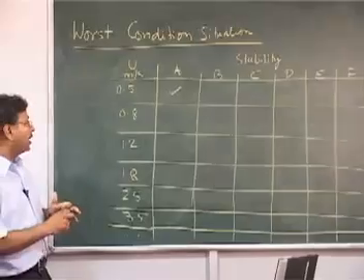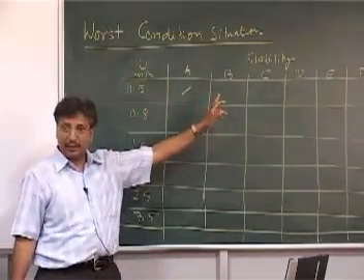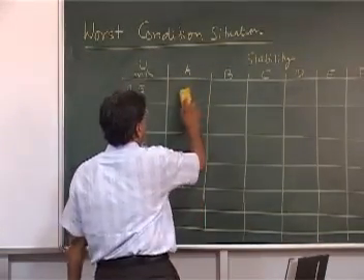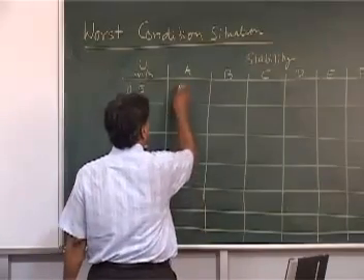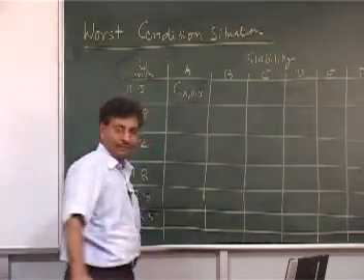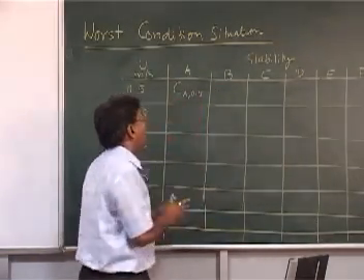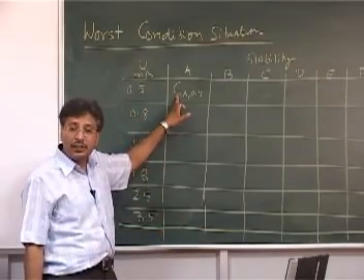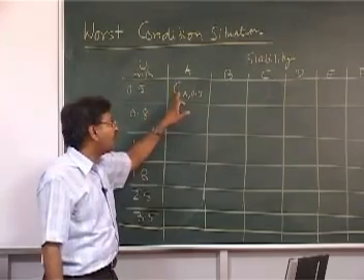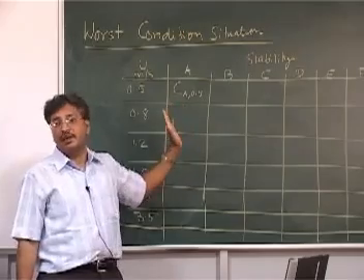I can write some number here. And I can ask my computer to do the same calculation for stability B. Let's write here, we are talking about C max A at 0.5. This concentration is the maximum concentration for this situation. And how did we get the maximum concentration? We have implied sigma z equal to 0.5 h.